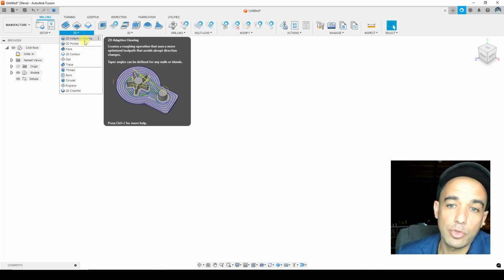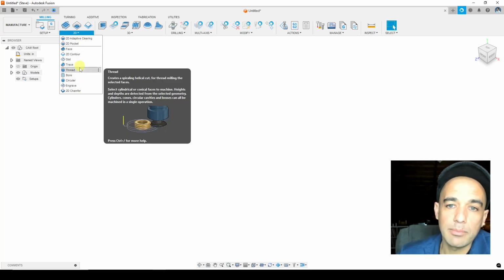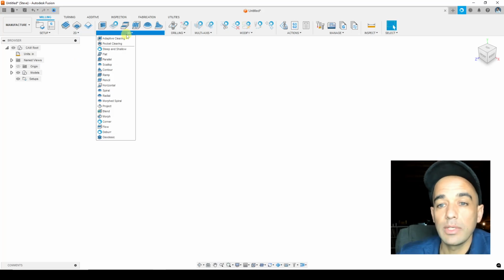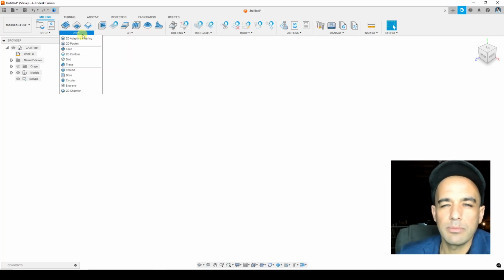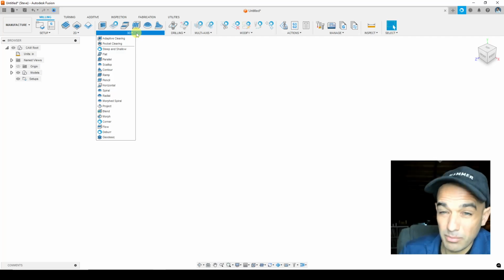So these are a list of different types of toolpaths, and as we go through the projects, we are going to use all these different toolpaths at different times. The next section is the 3D toolpaths. So they really separate these 2D and 3D toolpaths because they are quite different. 3D toolpaths are primarily used for finishing what we call 3D surfaces. 3D surfaces are ones that have kind of a dynamic Z. So that means kind of like maybe like a curve that happens in Z, so that in order to make that toolpath, the machine needs to move dynamically in X, Y, and Z simultaneously.